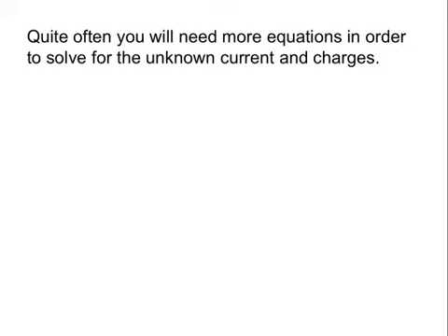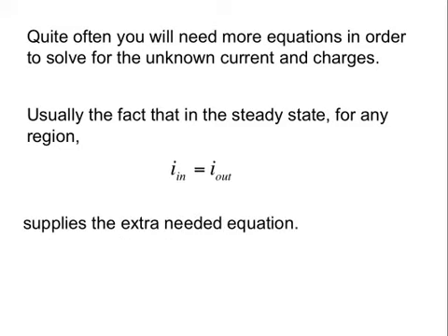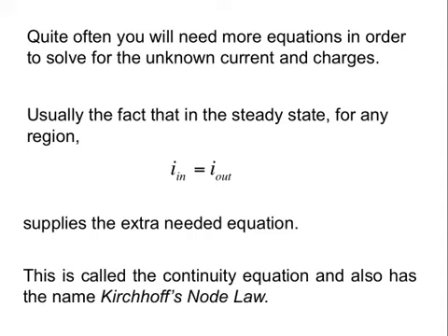Quite often you will need more equations in order to solve for the unknown current and charges. Usually, the fact that in the steady state, for any region, the current in is equal to the current out, supplies the extra needed equation. This is called the continuity equation and also has the name Kirchhoff's node law.